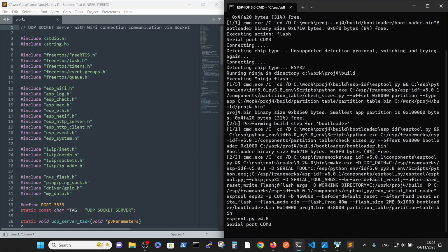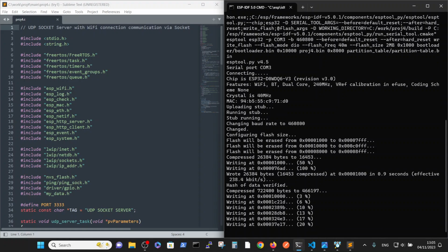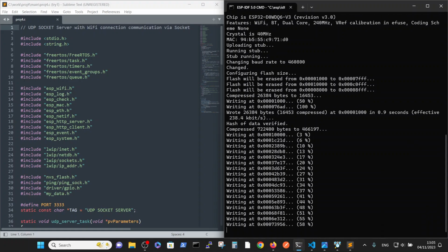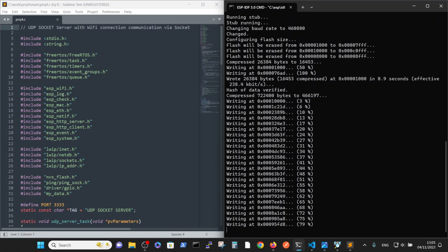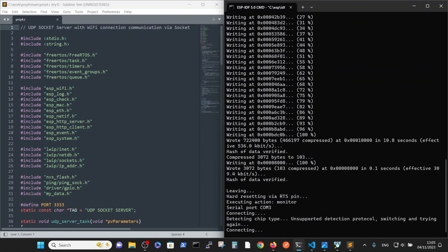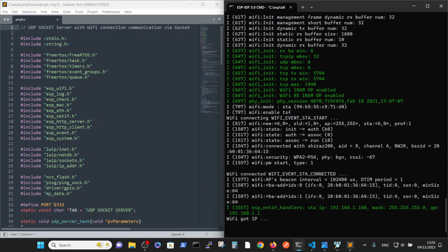Like in the previous video, it's important to take from this installation a board name, so that we will be able to find its IP on the net, because the IP addresses are dynamically allocated. The port we can define here in the software is 333 in our case.